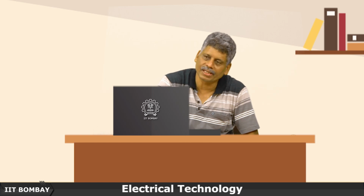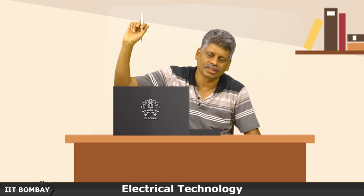If you recall, I had said that three phase systems, especially when you are dealing with balanced system, then the three phase system will have a constant instantaneous power, while the instantaneous power in the single phase system is fluctuating. In the three phase, it is smoothened out, and you get a constant three phase instantaneous power.